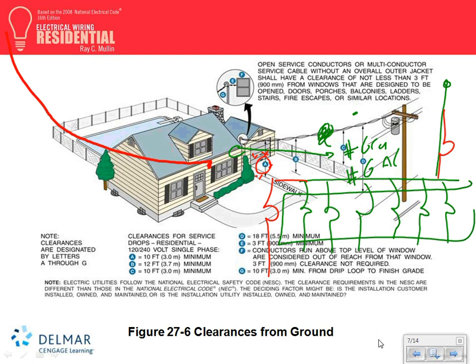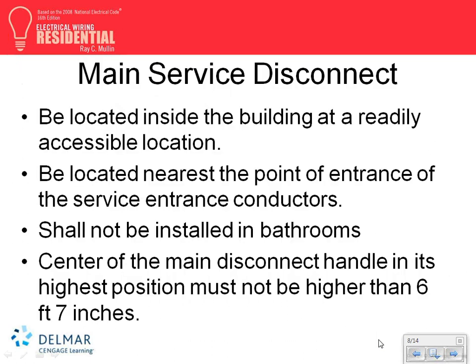Why is it that they make you put a 200 amp disconnect on the house? They make you put a 200 amp meter. Yeah. Future expansion. That has nothing to do with the code. In the future, if you change a 100 amp panel into a 200 amp panel, they don't want you to go change the meter. Oh, they're saying minimum from the meter to the panels 100. The meter will be a 200 amp, but the panel will be 100 amp.